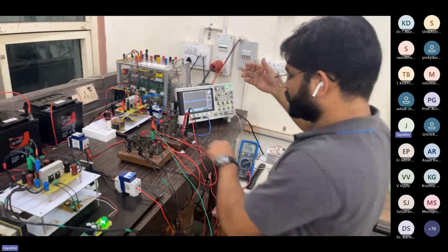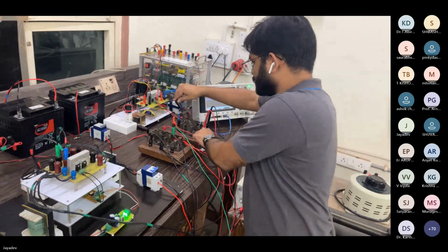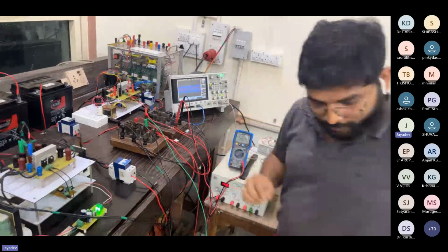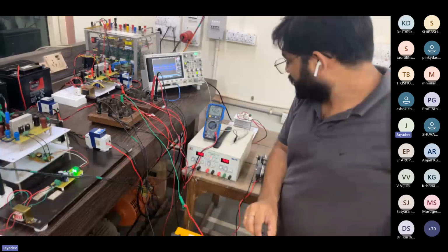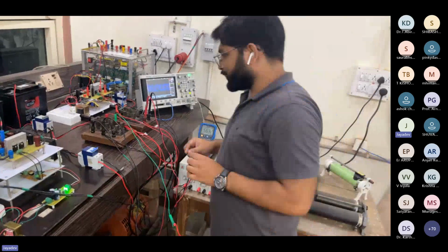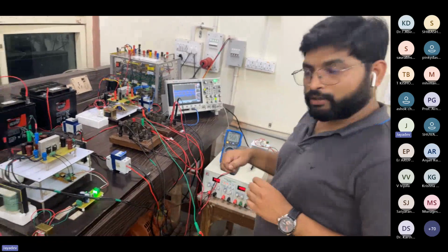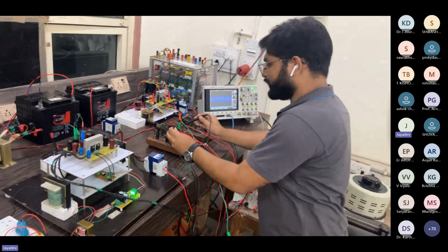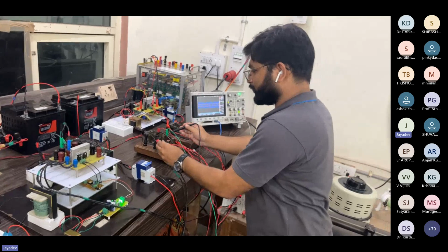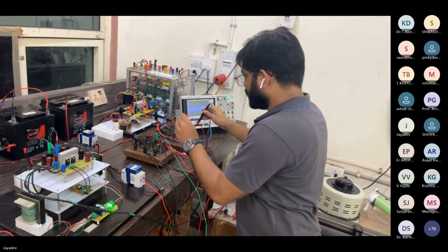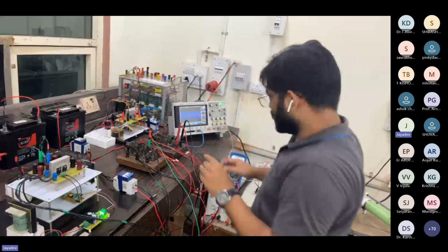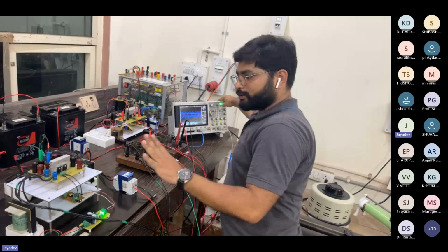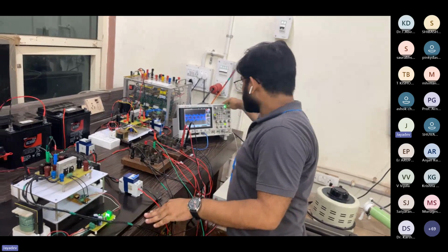Then we will integrate with the Pico-hydro. See, the voltage is 46, because of the resistance value. After connecting, we can remove some of the resistance. But I am not removing any resistance, because when I have to disconnect, the resistance should be connected at the output. Otherwise, for the buck converter and SEPIC converter, there is a chance of capacitor loss.